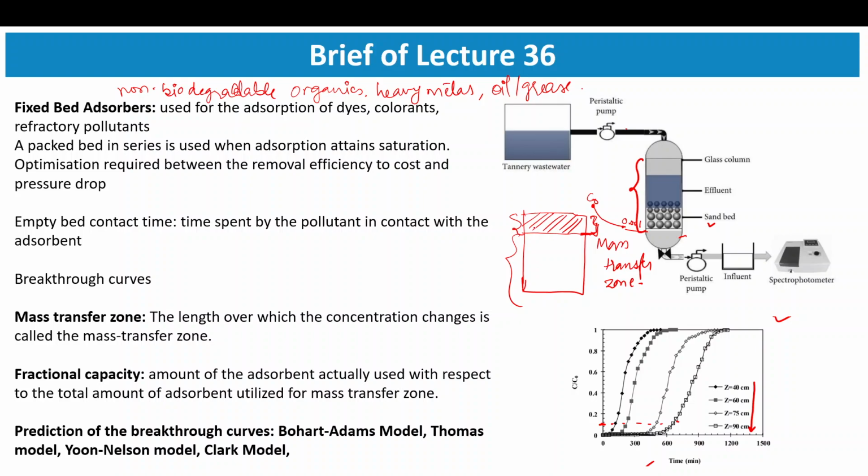Now, because the adsorbent has some capacity to adsorb, this portion will tend towards saturation, and this mass transfer zone will keep on moving. Let's say it was here, next it will be here, after some time it can be here. Ideally, the mass transfer zone moves like a wave moves, so you can say it's a wave front as well.